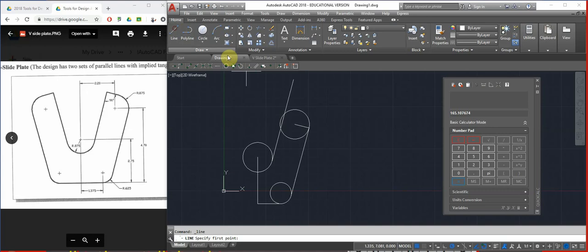I'm going to select a line, select tangent to this, and down here type at, which means relative, let's say 2 inches long, angle, which is the polar, and then paste. See this 165? It's the same as the number I pasted. I hit enter, and I have my angle here.